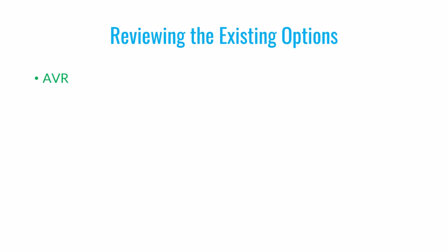Now let's dive into the details of the AVR processor. The AVR processor has a clock speed of 20 MHz. Assuming that each addition and multiplication instruction takes only 1 clock cycle, we can calculate that each instruction requires 50 nanoseconds to execute.